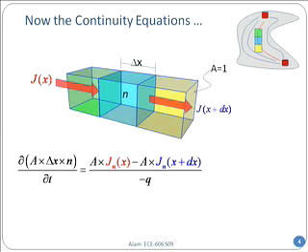Now, how does it relate to the current? Well, that depends on whether the number is growing or coming down, depends on how many are coming in and how many are getting out. Just like in this room, let's say students are constantly flowing in and some of them are leaving. So the number growth within the room will depend on the flux of electrons coming in and the flux of electrons getting out. Now I have divided it by minus q in the denominator because these are electrons and I want the number. In J sub n, there is already a minus q. Remember that this is because it's the electron current density.